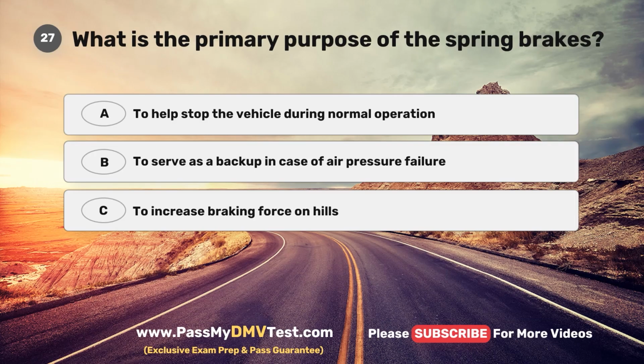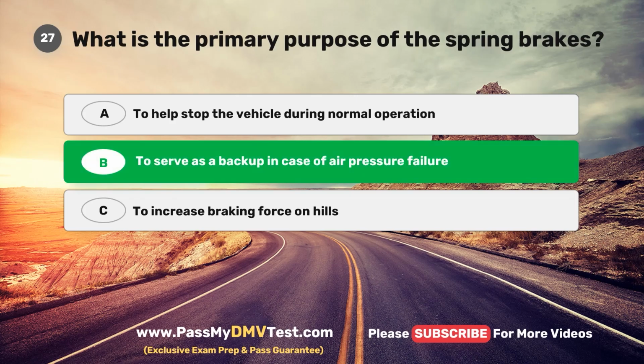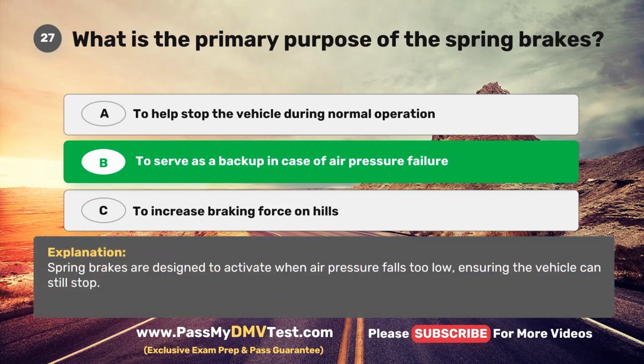Question 27. What is the primary purpose of the spring brakes? A. To help stop the vehicle during normal operation. B. To serve as a backup in case of air pressure failure. C. To increase braking force on hills. The correct answer is B. To serve as a backup in case of air pressure failure. Spring brakes are designed to activate when air pressure falls too low, ensuring the vehicle can still stop.